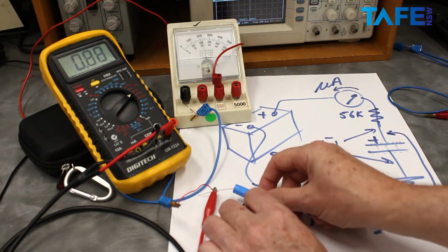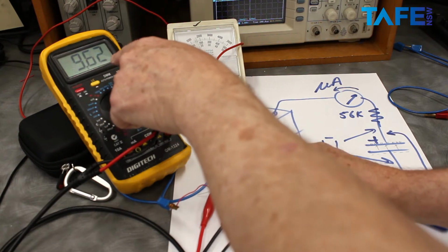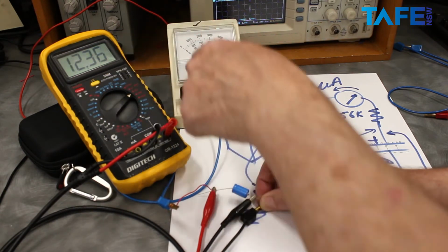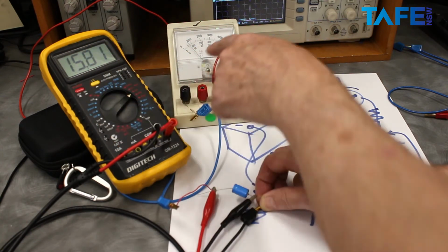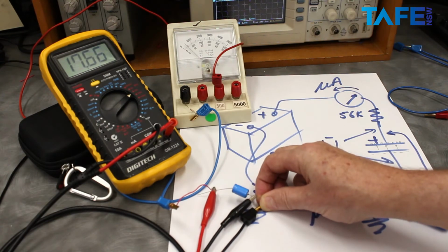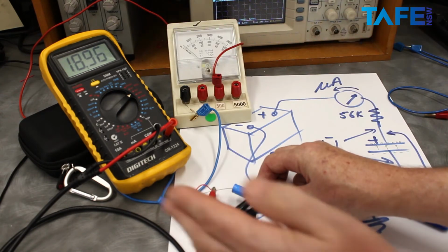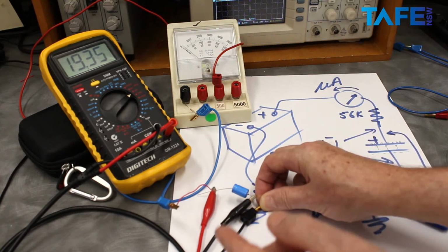All right, let's put some current on that. Very quickly up to 5 volts, 8 volts, 9 volts, 11 volts. I can hardly keep up. 13 volts, 14, 15. Current coming down rapidly. Now things are slowing right down. We had a massive dramatic surge in the voltage across the plates in the first second or so, and now towards the end things slow right down. And that's what we said.